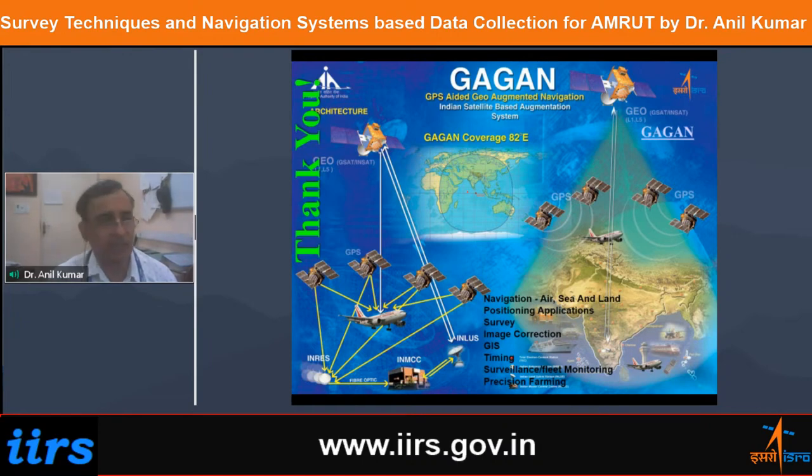I've not gone much into mathematics, just given you an overview, an idea of surveying techniques, what we require basically if you want to locate what an object is and where it is, its coordinates. So we can use a plane table survey or chain survey or theodolite survey. Best is nowadays people adopt the total station, which can do everything in the field and can prepare very large scale mapping. And then I went for GPS.